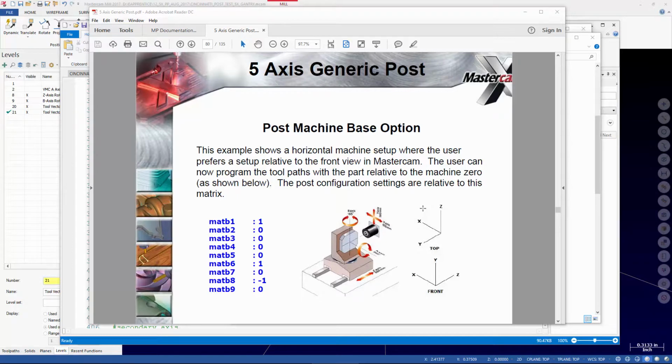Mike asks a question. We just got a Doosan DNM350 with a Fanuc 0i control, and apparently it is a 4+1 machine, meaning it can only move 4 axes, any 4 as I understand it, simultaneously. We don't do a whole lot of actual simultaneous 5-axis toolpaths, but I'm wondering how exactly would I go about restricting the post to output 4+1? Is that handled in the post or in the 5-axis toolpath parameters?